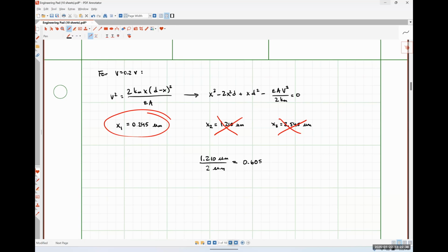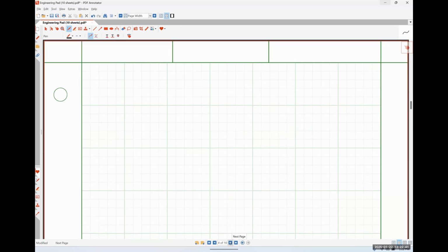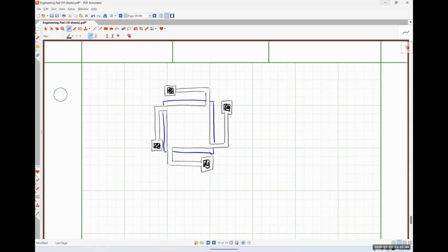All right, so I'm actually going to jump back to that picture that I drew to explain why our spring doesn't necessarily electrically link our top plate to our bottom plate. And I'm going to throw some dimensions at this thing. So let's say that our plate area in this case is 500 micron by 500 micron. The distance separating our plates is 1 micron, and our mechanical spring constant is 20 newtons per meter. So fairly stiff spring in this case.